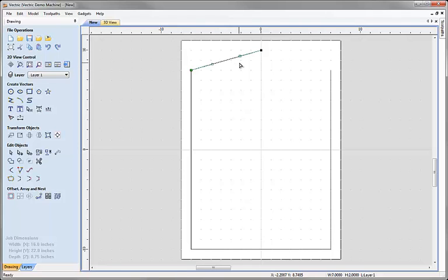handles here. And now what I can do with the mouse is click on these handles, and I'm just going to drag it so it's in a horizontal line from the node here 3 inches over. So 1, 2, 3 using the snap grid. The same with the top here, 1, 2, 3, and then let go with the point snapped there. So I'm happy with my line. I'm going to go back to selection mode. I'm going to hit escape on the keyboard to do that.